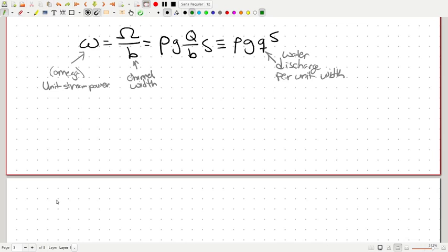And therefore, any expenditure of potential energy into kinetic energy, rather, should relate to the erosion of bedrock, which is causing formerly inert mass, so formerly stationary mass, to become detached and then to start moving downstream. And that will eventually relate to erosion, right? And give us some relationship for bedrock erosion.